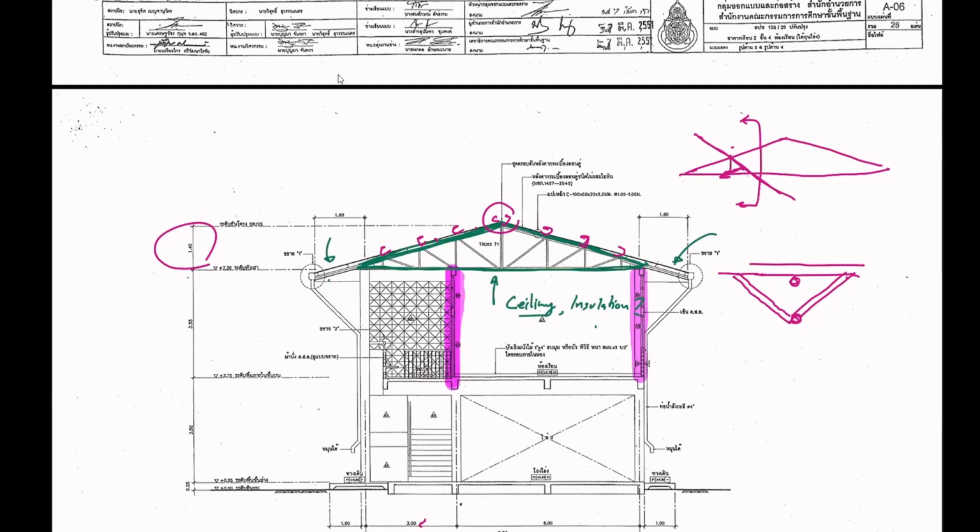Okay, that's one thing. Now, the second thing: when you use a computer program to design your truss, computer programs now are pretty smart, and will give you the option to include the weight of the truss members. Some do not know this, and they go on and try to use the computer program to design a small roof like this. They end up having bending moment in the member and they get shocked. So what is going on here? How can my truss have bending moment? Or some are not even aware of it at all.